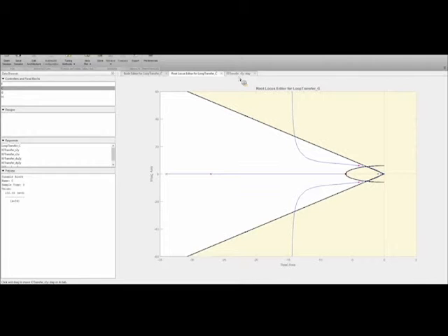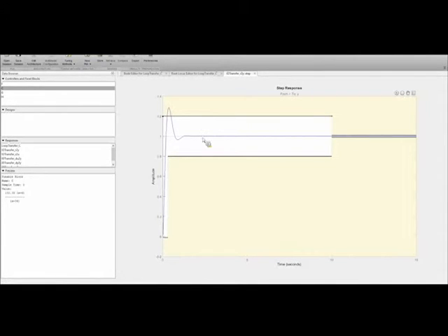So if we look at our step response, we see that we meet the rise time just fine. We're a little bit high on the overshoot. Okay. So this, I would say, gives you something that's very, very close. We are much better than we were with this design methodology. If you ever want to exactly get this, you have to do a little bit of manipulation to get this to work.